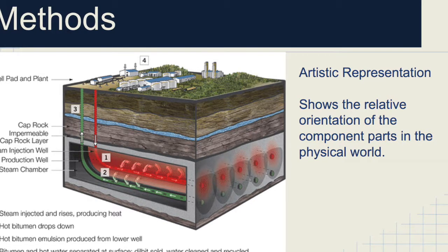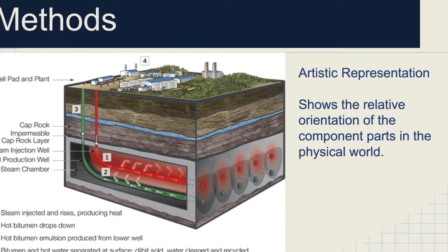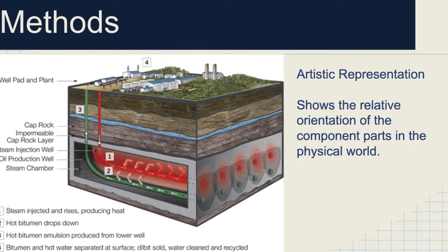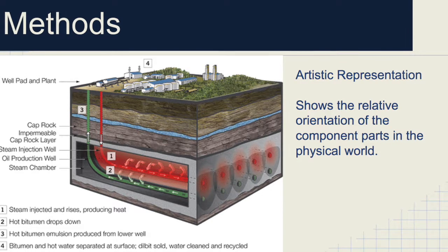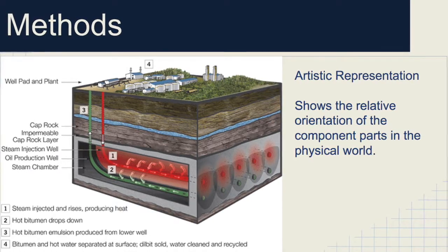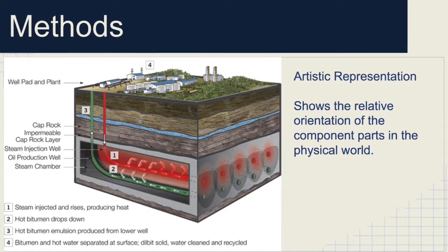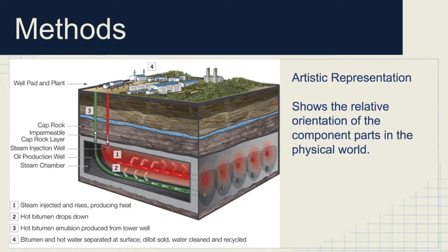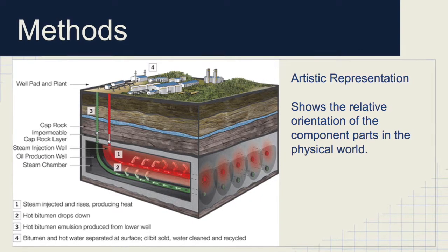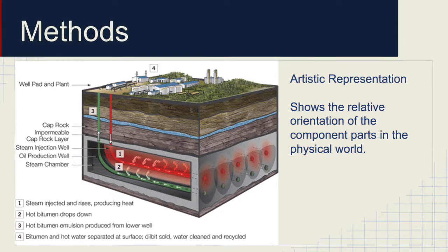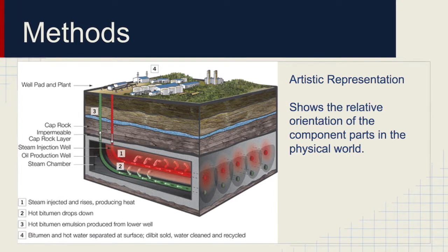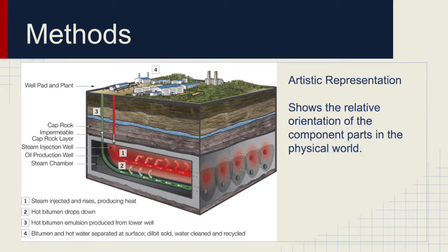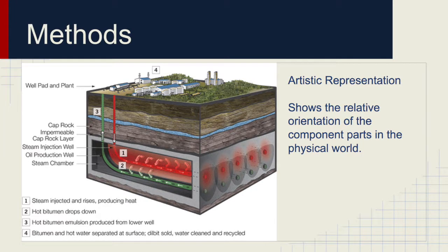Thanks, Summer. I will now discuss the methods of steam-assisted gravity drainage. SAGD uses a simple method of two horizontal well bores to reach unconventional oil deposits. The deposit is drilled into two wells, approximately 4 to 6 meters apart. The steam is injected at high pressure to fracture the rock deposits, and reduces the viscosity of the target oil deposit. Once the emulsified mixture of steam and bitumen is at a sufficiently low viscosity, the gravity drainage aspect of the process comes into play. The emulsion is then pumped out of the deposit after having settled into the lower wellbore.